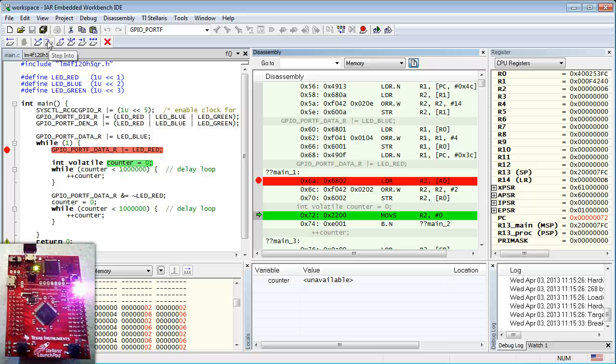But imagine that each bit could be accessed separately through its own unique address. Or better yet, every possible combination of GPIO bits would have its own unique address. Then a single atomic write operation to this particular address would change the selected bits without disturbing any other GPIO bits. In this lesson, I will show you how the Stellaris GPIO hardware allows you to do exactly this, so that you can replace the typical read, modify, write sequence with a single and atomic write operation.